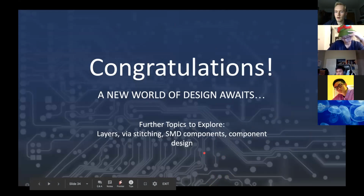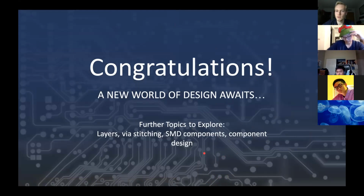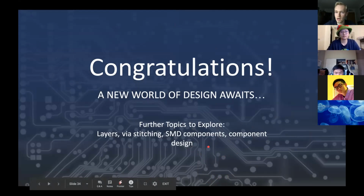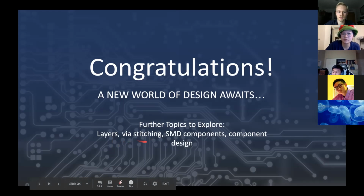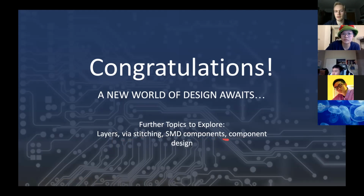All right, so now we've gone over the concept of how to do this whole PCB design thing, and we're going to go over a tutorial of that hands-on in a little bit. Some future topics that you might eventually want to explore are more layers, like the versions of Eagle that you pay for can give you access to, I think, up to 10 layers, which sounds really complicated, and I imagine it is. Also things called via stitching, which we won't get into now, surface mounted components, and designing your own components, which is actually a thing you can do on Eagle.